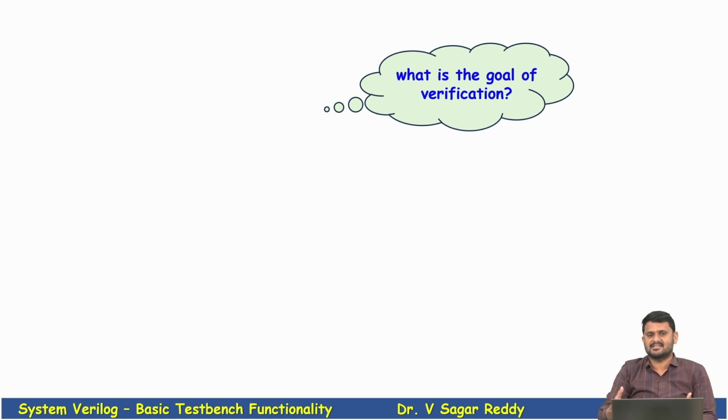When we design any digital circuit, for example, an adder, counter, or a processor, we first write RTL code using SystemVerilog or Verilog. But just because the design is written and compiles correctly doesn't mean it will work correctly in every case. That's why we do verification, to check the design's correctness and reliability before fabrication.